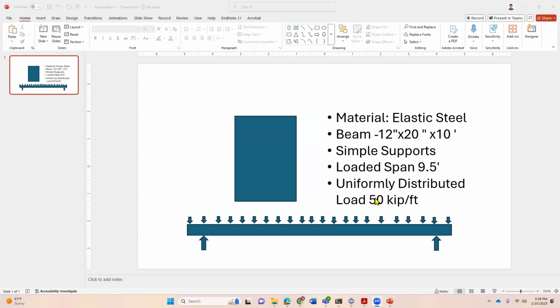So I hope it will be a great lesson for all the engineers, and also for those who are learning Abaqus. It will be really helpful too. After this beam, I will model a beam with elastic plastic material, that's actually steel. So steel is not elastic, right? After yielding, it shows some hardening, and beyond that region, we call it a plastic material, and sometimes we just simplify it with bilinear elastic plastic material.